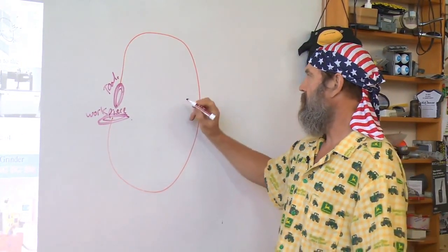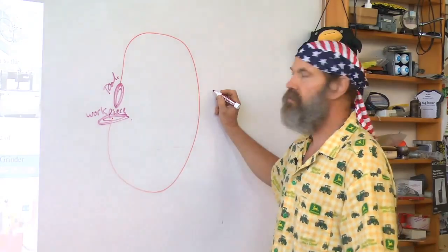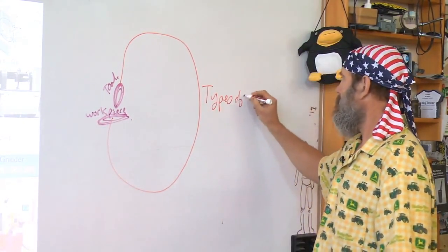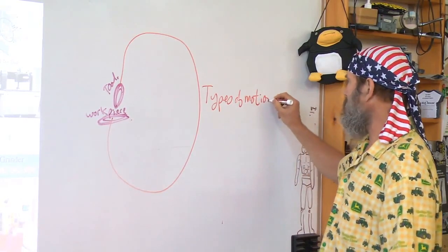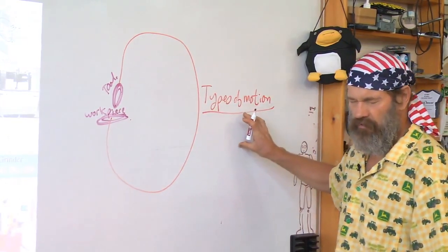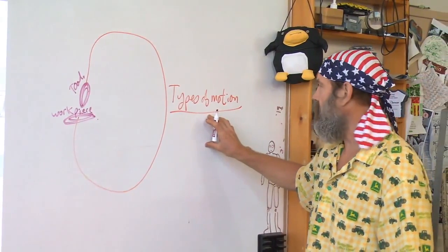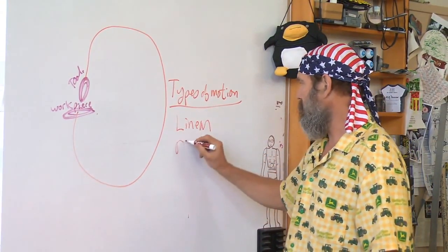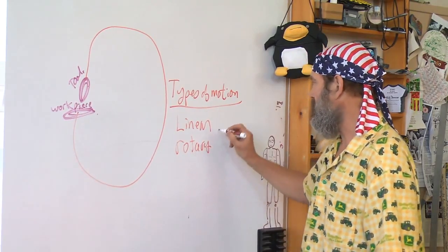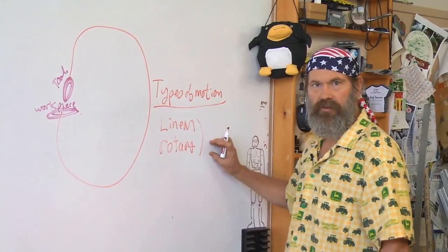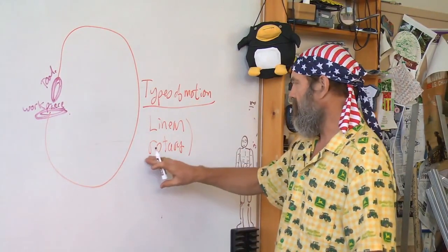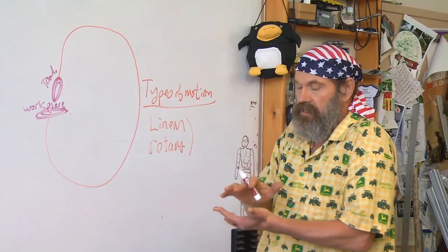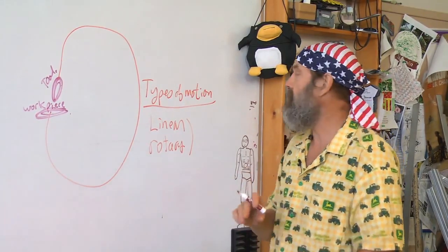What I like to do when I'm designing a machine is literally I have the tool, the workpiece, and I'll start writing down my requirements for the types of motion. And often this will come from your concepting of the machine itself in terms of am I going to have linear or rotary motions and what combination. I can have all linear or all rotary or some combination. Remember from topic 4, multiple rotary axes at the same point would give you spherical ultimately.